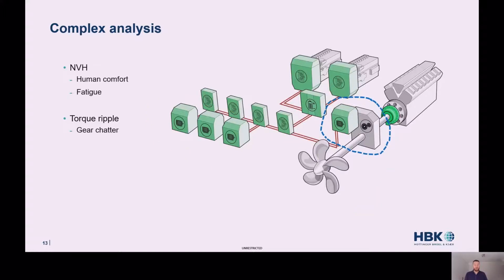It is interesting to do on a system level, where different vibrations can overlap, amplify and cause trouble. With our electrical drives exciting components causing vibrations, we can find correlations between frequencies found in the drive current measurements and the actual vibrations measured at the machine or the structure. Correlating these can help identify and fix such issues, for example, by changing the machine control strategy or the inverter software, which demonstrates the use of combined electrical, power and NVH measurements.